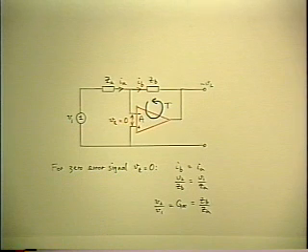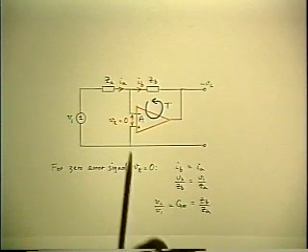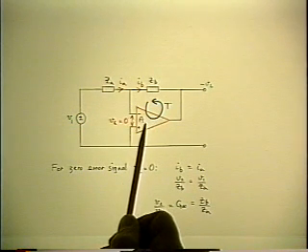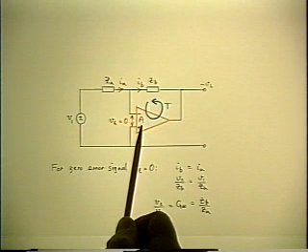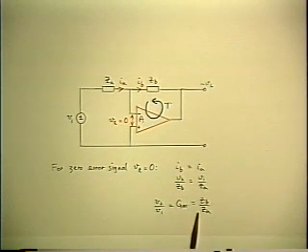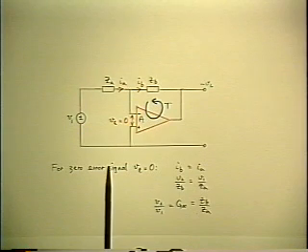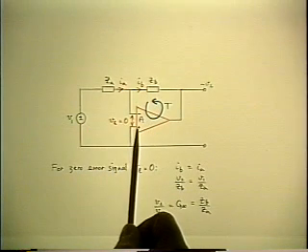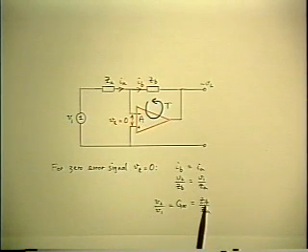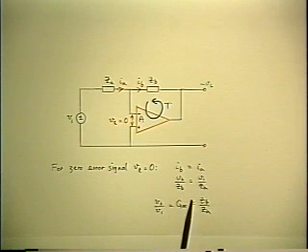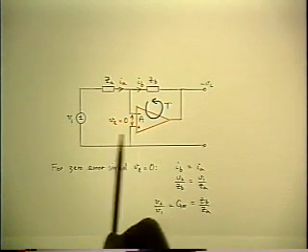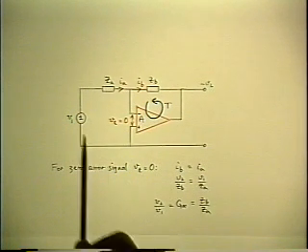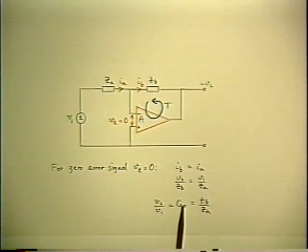But once again, what you really calculated is G infinity, because it embodies this assumption of infinitely large gain of the forward path. So it again neglects the fact that there is a D factor which comes in when the amplifier gain drops off at higher frequencies. So the same result. What you've calculated is really G infinity, and you oughtn't to forget the other part of it, which is that the T and the D ultimately will go away, and the actual closed loop gain will cease to be equal to this ideal value.